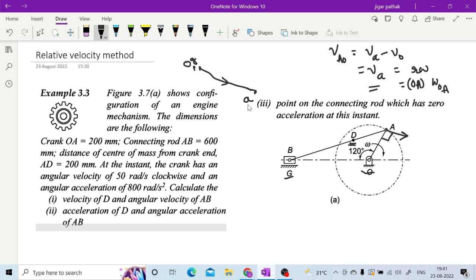Once you have drawn this, then if you think of the velocity of point B with respect to A, it will be perpendicular to this link length BA, right? Once you have all the instruments with you, like a ruler or scale, you can transfer the direction from this image to this image, and take the perpendicular to AB and plot it like this.